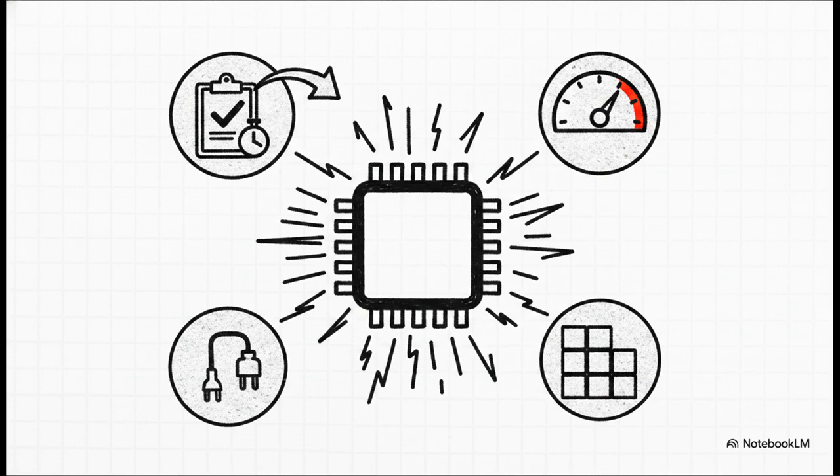Let's zoom in on that very first hurdle for a second, hardware initialization. The bootloader configures the CPU speed, sets up memory registers, turns on the caches, and readies the serial port so we can actually see diagnostic messages. It also performs a power-on self-test, or POST. And hey, fun fact, if you ever want to shave vital seconds off a device's startup time in the field, this post-diagnostic can sometimes just be skipped during warm boots. Pretty neat trick if you're optimizing.